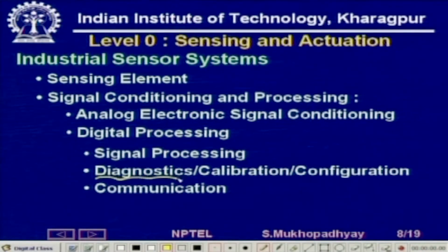So, that is diagnostics. Sometimes sensor characteristics degrade. For example, suppose a sensor develops a bias. You can have algorithms to actually detect the bias, and you can do its own calibration. A sensor can send information, or can be interrogated, and you can find information that it has developed a bias. So, its readings will be interpreted accordingly for greater accuracy.